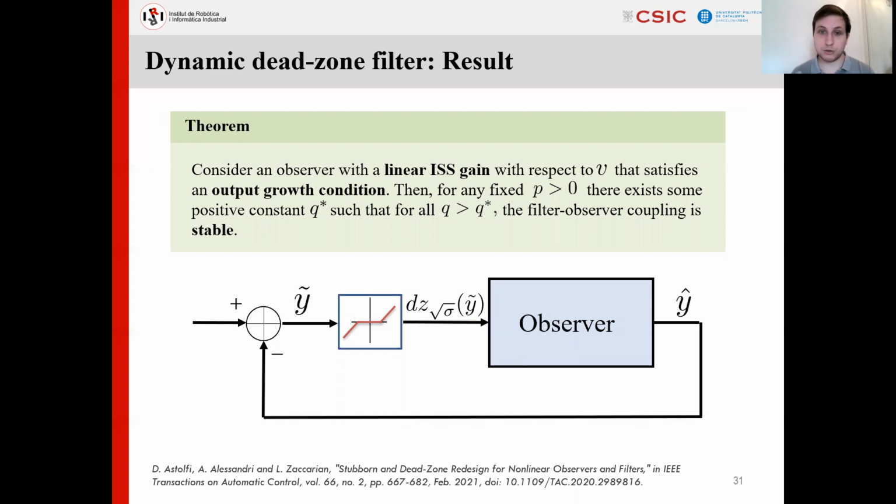And I thought that it was interesting to include this result in the thesis because by following the paper presented here, you can actually show that under the same assumptions as in the proposed low-pass filter observer, meaning that the observer satisfies a linear input to state stable condition and a particular output growth condition, then you can always tune the dynamic dead zone filter to guarantee the stability of the coupling. And this is an interesting result because with that, what you can actually show is that you can combine these dynamic dead zone filters with the proposed low-pass filter to get really powerful filters.